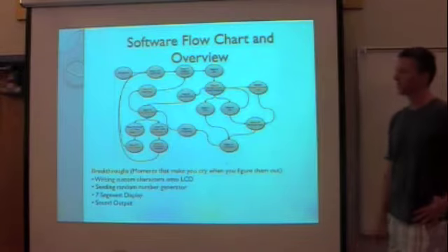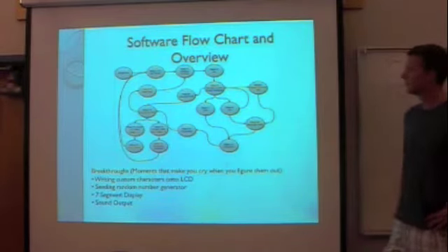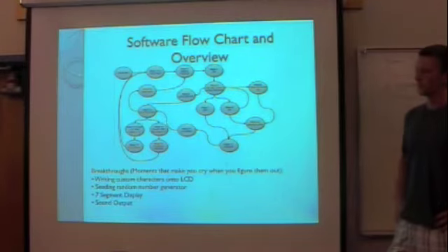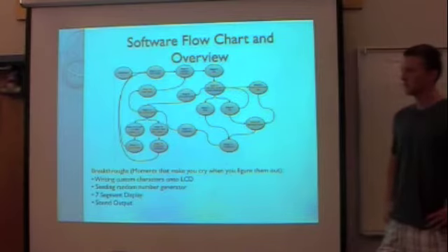Alright, so this is the software flowchart. Before the game starts, during initialization, you write custom characters into the LCD CGRAM addresses so that we can display card suits like diamond, club, heart, and spade. Then it goes into stages 1 and 2, which is the title screen.